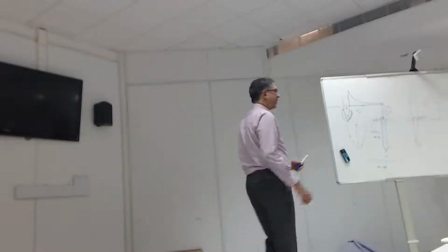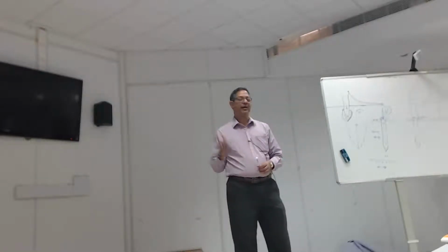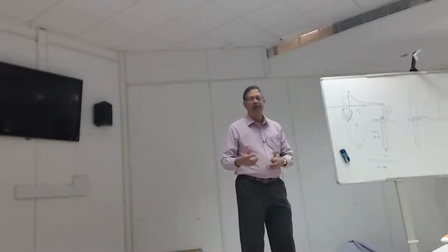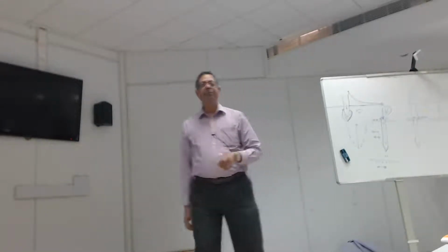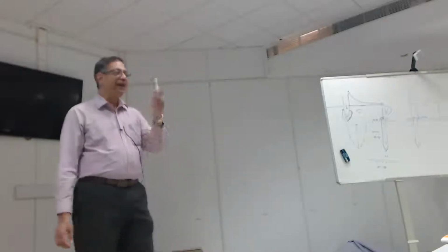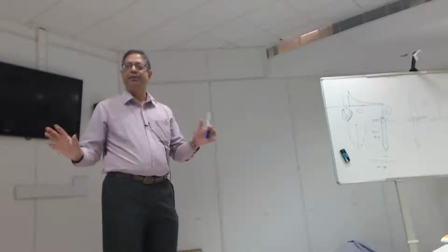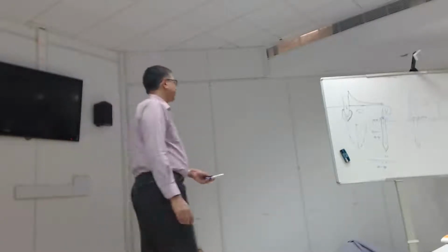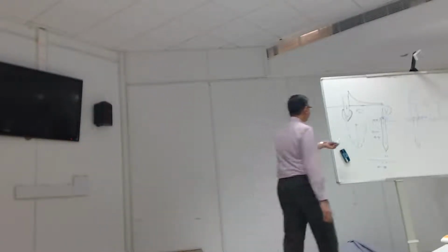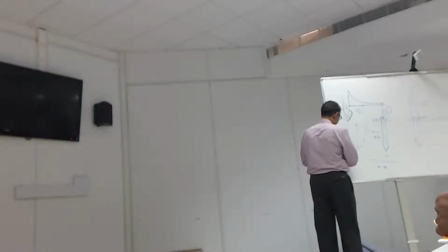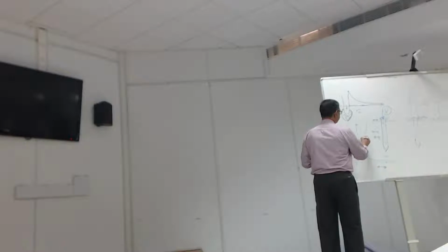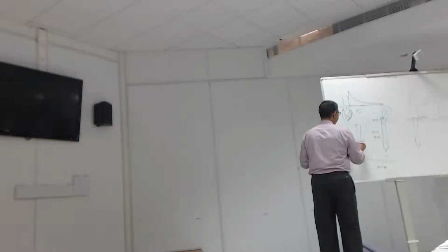Then you have this other component called kinematic loading. Kinematic loading comes simply because the pile and the soil are not one and the same. They are different materials, with different densities, and if the soil wants to do this and the pile wants to do something different, maybe it only wants to do this as a mode shape, there is this difference, right?